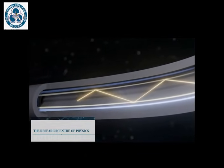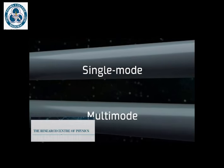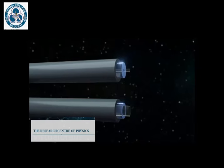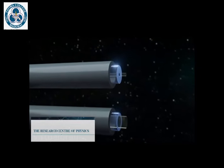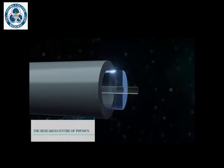In this way, when a beam of light enters the core, it will be reflected every time it reaches the edge with the cladding, being guided along the cable for long distances. There are two main types of fiber optic cables: single mode fibers and multimode fibers. These differ in the size of their core and how they transmit light signals.